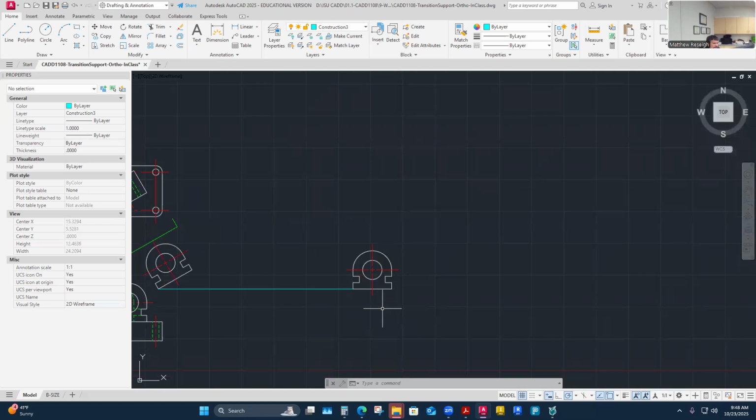What I want you to remember is, when you're drawing stuff, sometimes I have a little notepad where I note, okay, I rotated down 30 degrees or something. There were dimensions I'd keep track of with some notes. I just need to remember that because part of the view label is going to become, this is like a view AA, not a section or anything. So I'm going to say it's view AA, and it is rotated down 30 degrees, or just rotated 30 degrees.